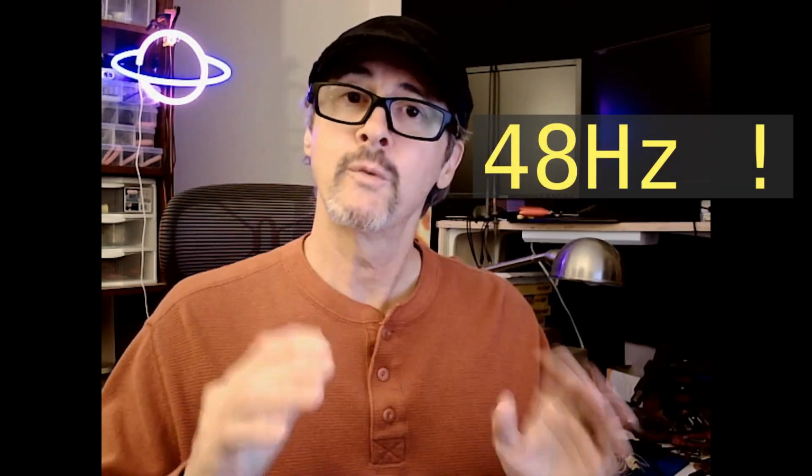Excellent. We have successfully synthesized our RISC-V processor, the Ranger RISC. However, we did so at a horrifically low frequency of 48 Hz. Now, as reported by the nextpnr tool, we can actually synthesize at 18 MHz. The problem is our core clock is 25 MHz. Hence, in the next episode, we're going to look at phase lock loops, or PLLs, and maybe we might interface to a SPI device. You never know.